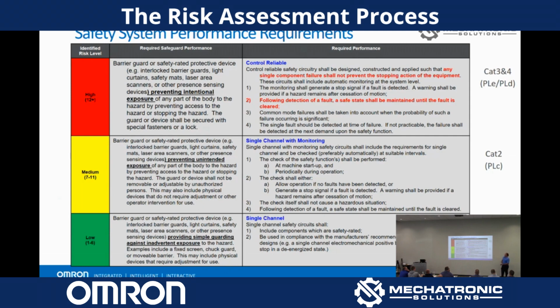Okay. And what I want you to know is that the performance level is the same. It's describing the same features that the ANSI one is, but it takes it a little step forward with respect to things like it also factors in mean time to failure of the equipment, okay? And it takes into consideration common cause fault and diagnostic coverage. So it adds a couple of layers on top of the ANSI standard, okay? Because the Europeans like people more than we do. Gotcha.